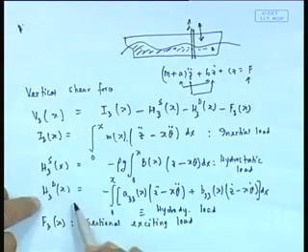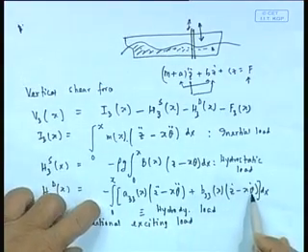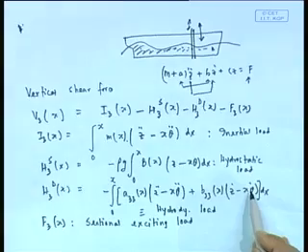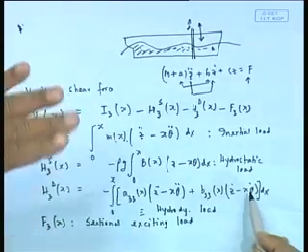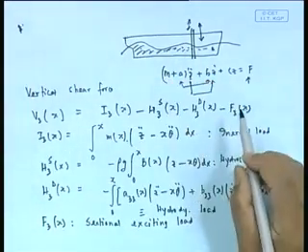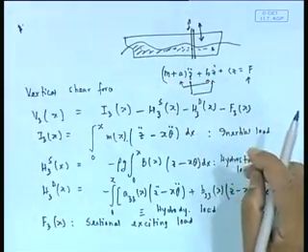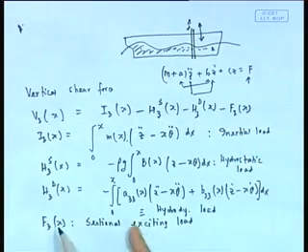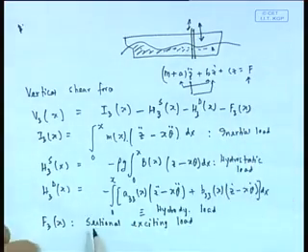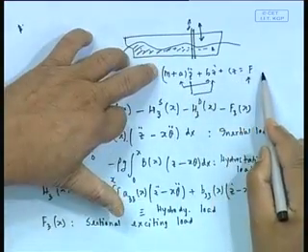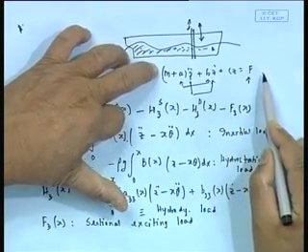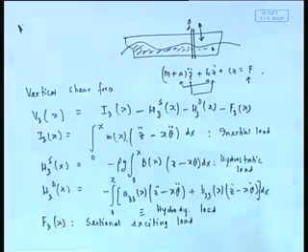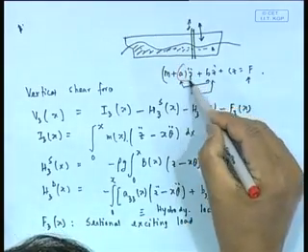Then we have this added mass and damping load. Remember, added mass and damping arise, and were also part of the load, because the ship section was moving and radiating waves, and that has altered the pressure field, and that pressure field again acts as a load. And of course, we have the exciting load. If you look at this equation of motion, we obtain the added mass and damping force, given by this part, that is AZ plus this part.